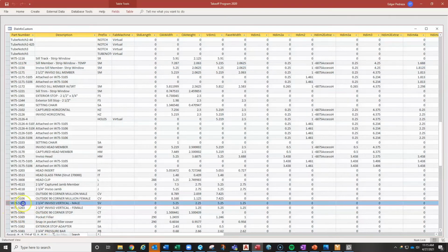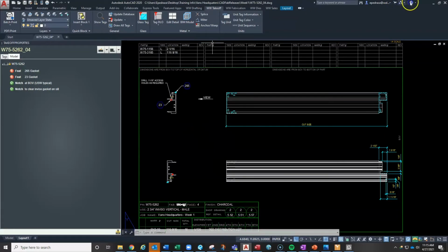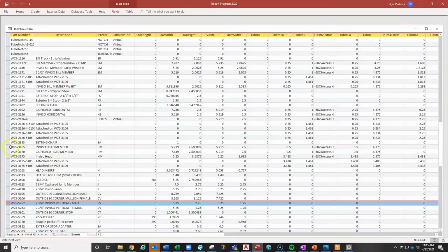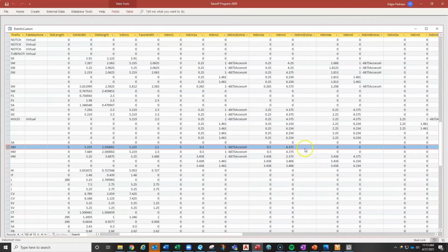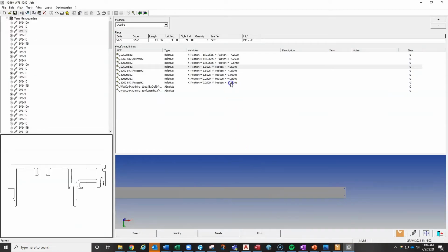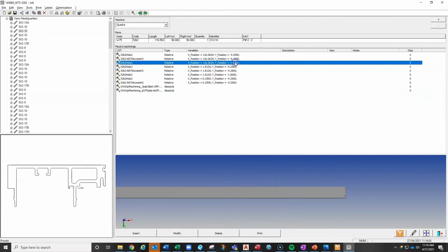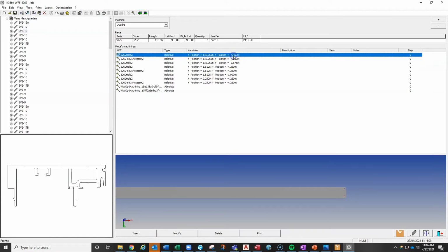So we're going to do 5262 and then get the v-dim1, so 5.25, and then we're going to calculate the y position. So let's see, it's a 3165. So 3165, and then we're going to subtract it by an inch again, and so it should be 4.25 for one of them, and the other we're going to subtract 5.25 minus 4.375. So we should get one that's 4.25 and 0.875 for the y position here. So 0.875 and 4.25. Perfect.